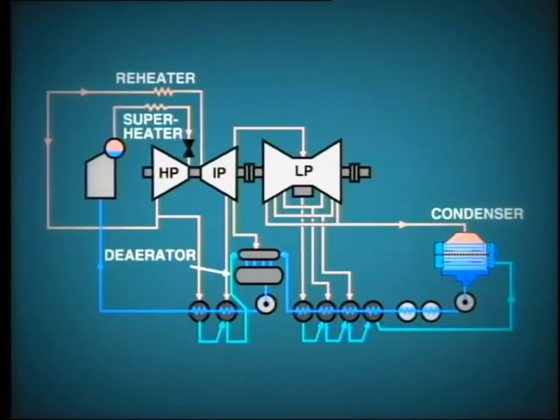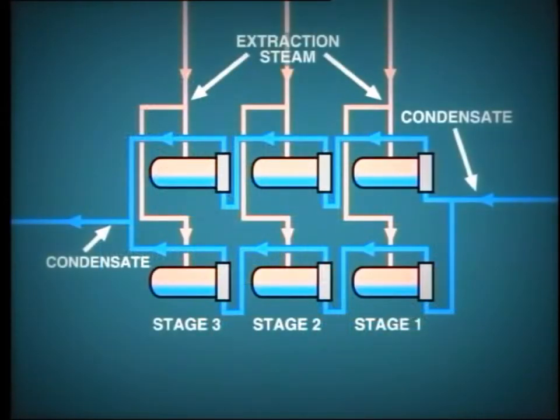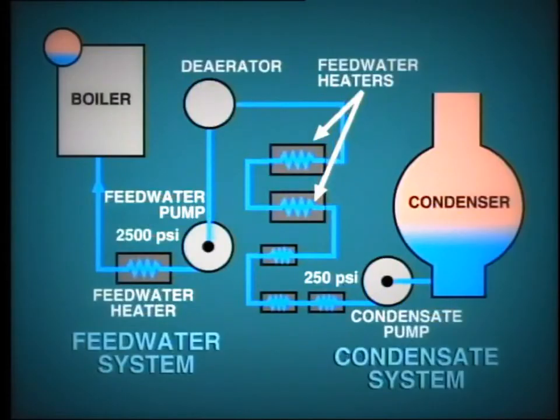Now, at this point, let's turn our attention to the feedwater heaters. In our earlier example, we looked at a system which contained 4 stages of feedwater heating. However, it is quite common to have 7 stages and even more. Moreover, in large plants, each stage may consist of 2 feedwater heaters. However, in all of this, the principle of operation is the same. So we will continue our discussion by looking at the 4 stages of extraction.